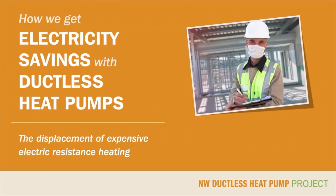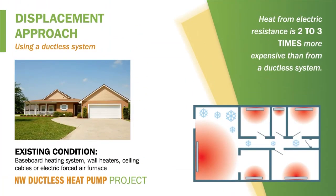Let's quickly review the displacement heating method, which is how we save electricity in the Northwest's ductless rebate programs. The Northwest Ductless Heat Pump Project supports the application of ductless heat pumps to save energy and make people more comfortable in their homes. Specifically, the project supports the displacement of electric resistance heat, which is produced by baseboard heaters, wall heaters, electric forced air furnaces, and ceiling heat. These forms of heating use electricity directly to produce heat, and it is 2 to 3 times more expensive to produce heat this way when compared to a ductless heat pump.